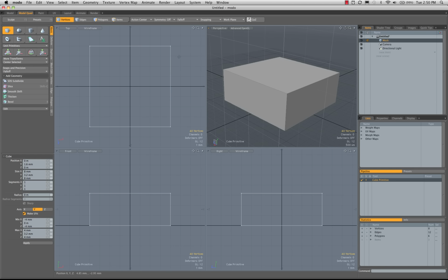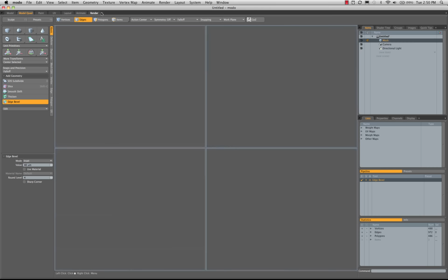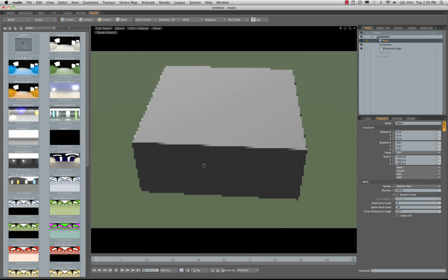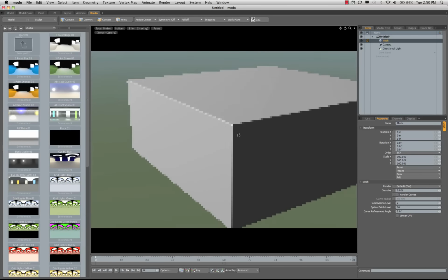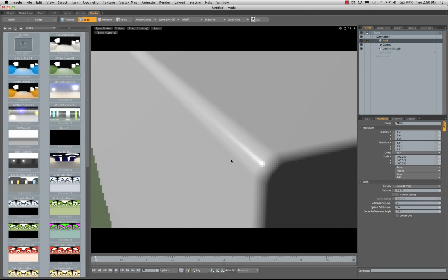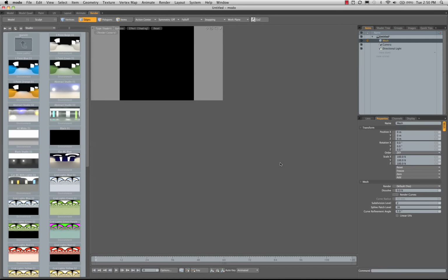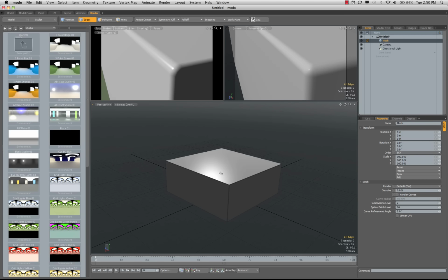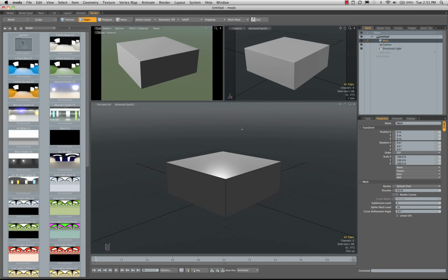And again, you might ask the question, why not just go into edge mode here and do a slight edge bevel? So why not do something like this? Here we get that same edge beveling, and we kind of get the effect. Now, the problem with this is that I did this at 4 levels of subdivision, which makes relatively dense corners. Obviously, you can go a lot more, but the closer in you get, this is going to look just chunky and not right. Plus, because of that faceting, you have to spend a lot of time messing with the smooth angles, and even then you're going to be missing some things that you would get out of a well done subdivision surface model. So let's undo that.